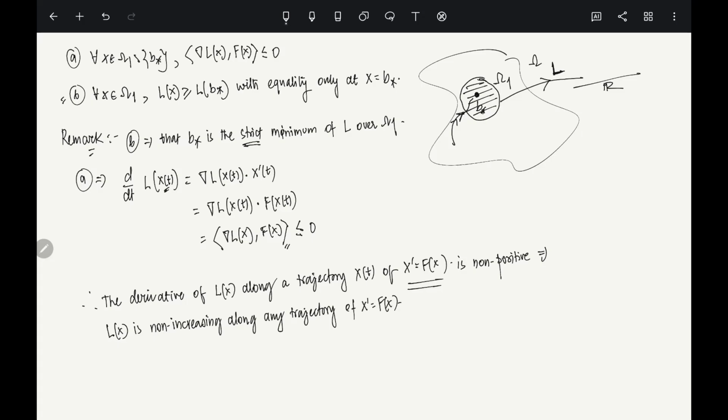Okay, fine. So what we did is we defined a particular kind of function which has some properties. Now the question is, what is so special about this? What can we do with this? This is the theorem which will guarantee that once you have a system with a Lyapunov function, it is going to be Lyapunov stable. So basically the equilibrium is going to be stable, in the sense we talked about in the last video.